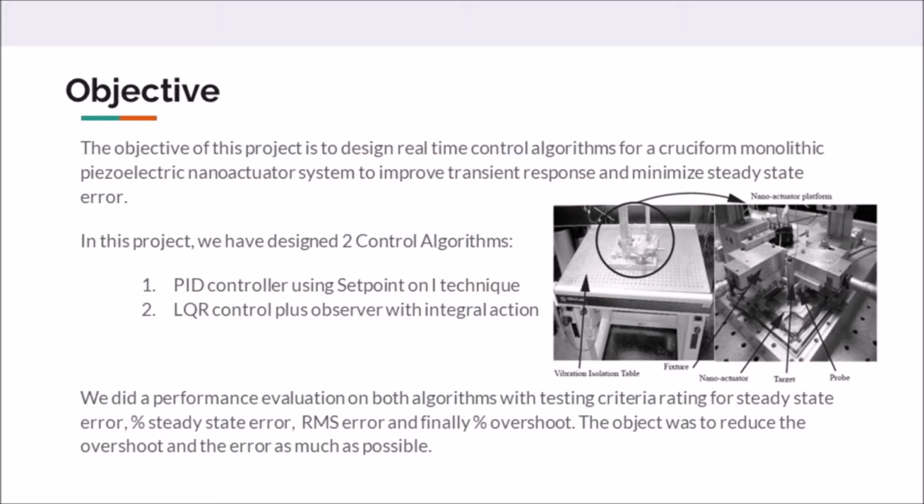Before we proceed, we need to realize that at the heart of the piezoelectric positioning technology is a piezo ceramic actuator. It has a crystalline structure which expands slightly when an electric potential is applied, known as the inverse piezoelectric effect. This property is exploited by nano-positioning technology. By changing the voltage applied, very precise control of motion can be performed.